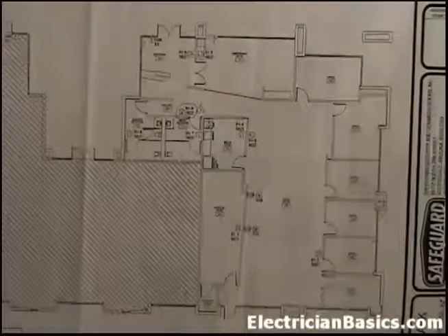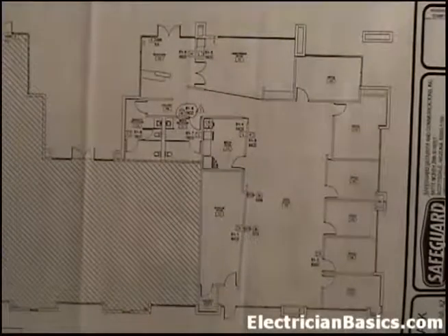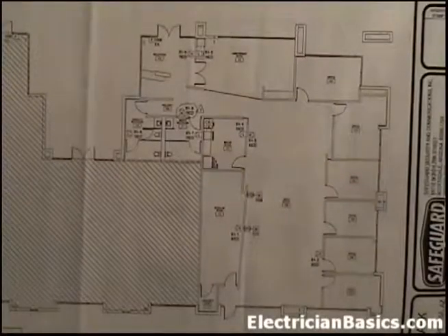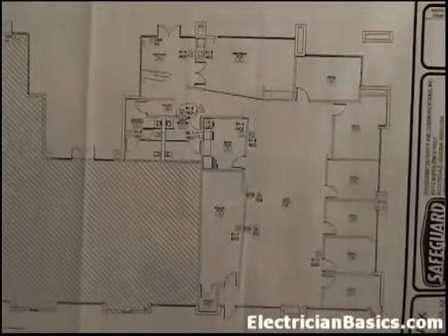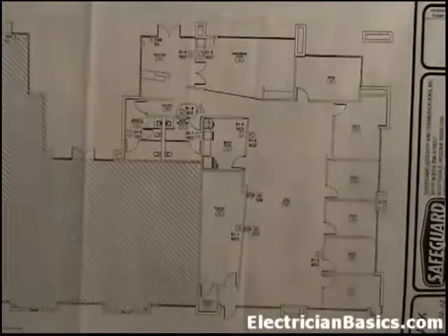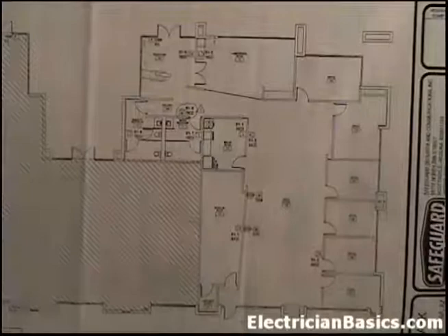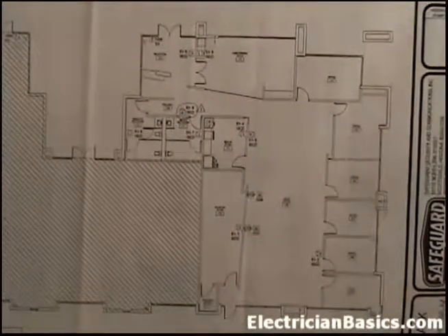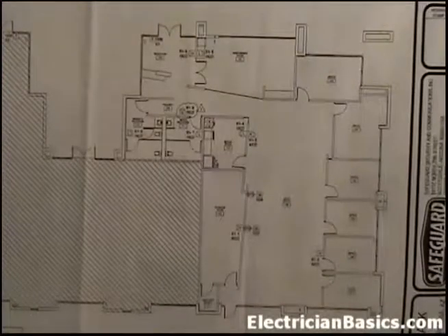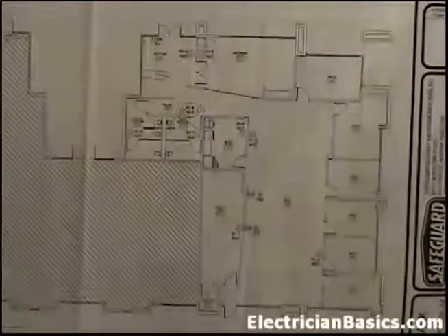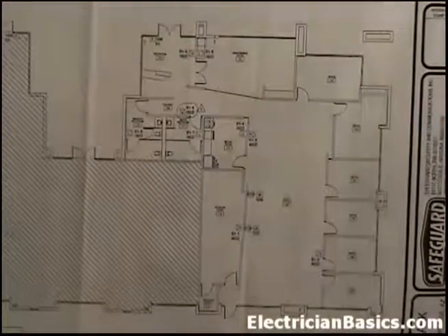When you get the plan, you have to look at it, especially if it's completely in conduit, where you have to have conduit from each of the boxes to the next box. That's where it becomes very important to run it in the proper order. What you need to do is look at this, see where your devices are going to be located, and then install it so that your conduit goes in the proper sequence 1 through 9 as you're told to on this panel, or whatever your panel schedule tells you to do. So that finishes up sheet FA02, the fire alarm floor plan for us.